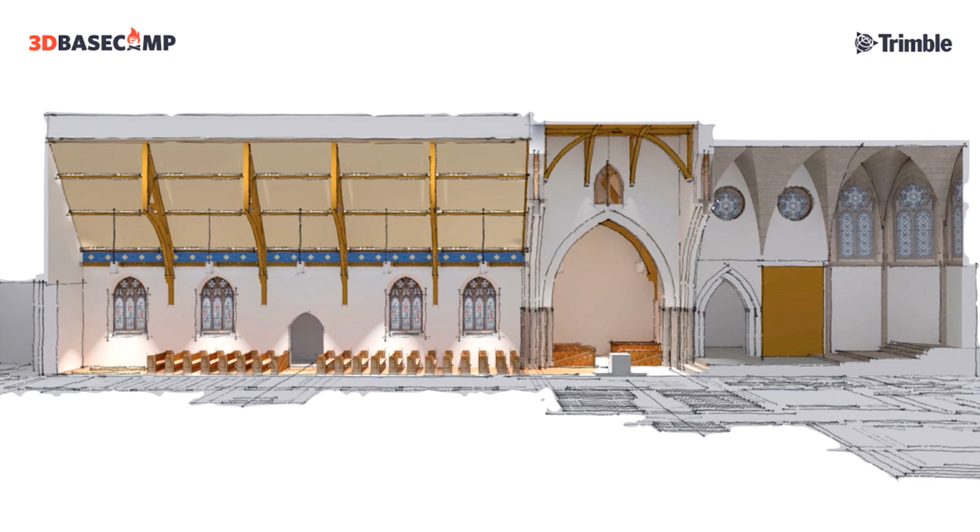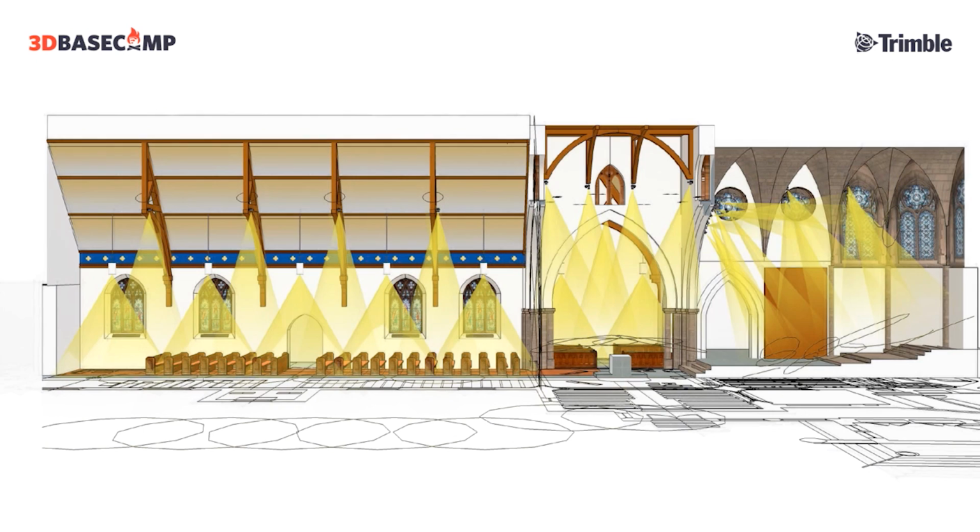That way, as I was making changes in one side, it was doing it in the other. And in something like this, you'll see we're not really creating the fixtures to begin with. We're just having placeholders for them. But here, using Podium and this section cut, we're at least starting to convey it. And this is actually just straight out of SketchUp. So instead of using the 2D gradient that I showed first, we'll create a big yellow cylinder and make it 20% opacity, just to show the angle and trajectory of some of that light, and to understand how we're going to layer some of the light within the space.